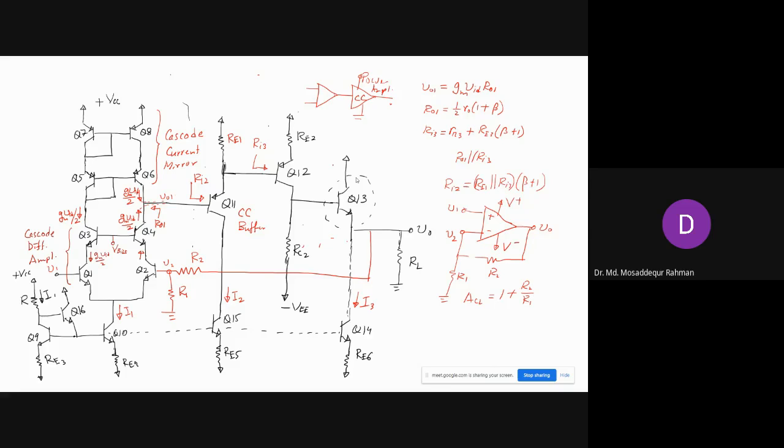But for the time being, just for your knowledge, you can use a power transistor in common collector configuration at the output of the amplifier to boost the level of the current and the level of the power. Okay, so that'll be all for this course.